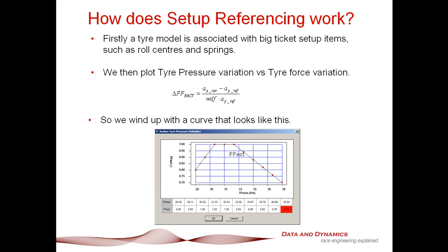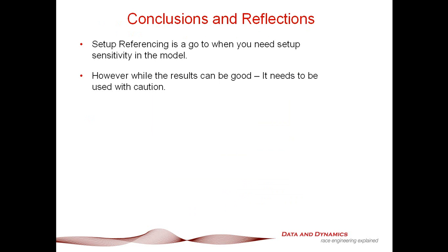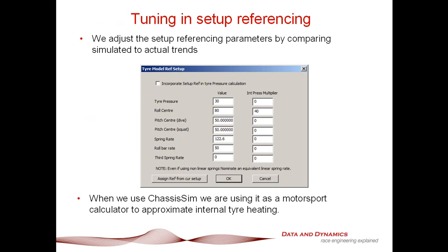So consequently, when constructing this curve, always do a proper tire pressure sensitivity sweep and make very sure that you're tuning this table to what you can see in your data.